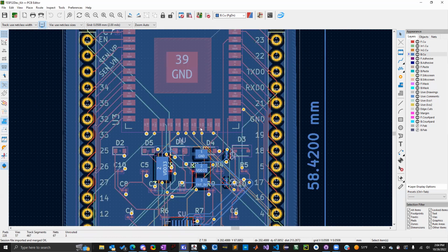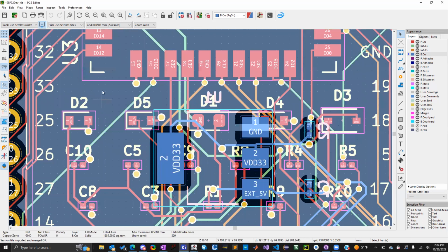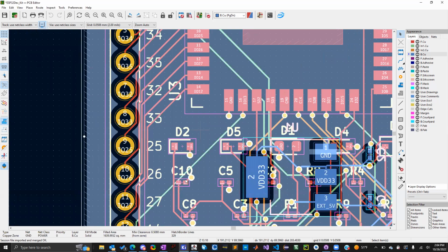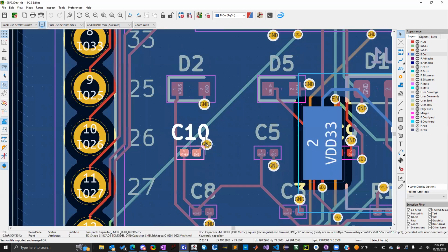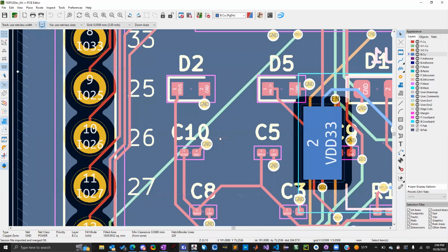If you put the ground pad in there before you go to the auto router, that works too, but there are some circuit designs that may require more intricate ground track placement, and which I would recommend not doing